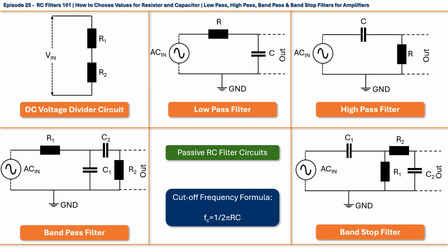The function of RC filter, as the name suggests, is to filter out the unwanted frequencies from the circuit. For both types of RC filters, the main parameter is their cutoff frequency. For low-pass filter, cutoff frequency parameter says that from that frequency and higher, signal will be attenuated, or simply put, the amplitude of the signal will be significantly reduced, and frequencies below cutoff frequency will pass unattenuated. Likewise, for high-pass filter all of the frequencies lower than cutoff frequency will be attenuated, or their amplitude significantly reduced, while all frequencies higher than cutoff frequency will pass through the filter without attenuation.